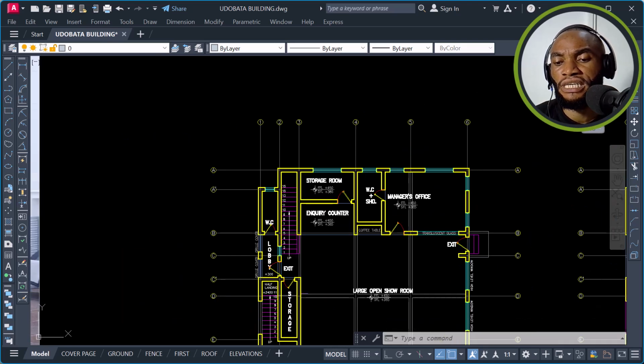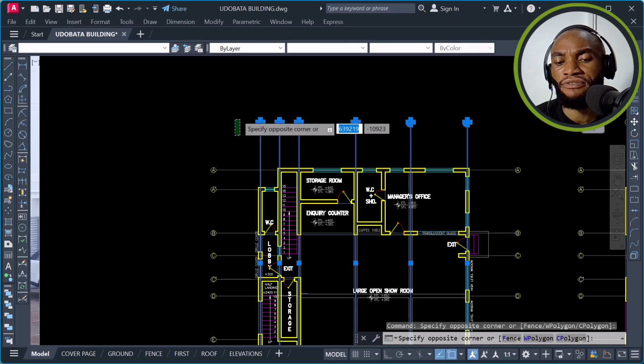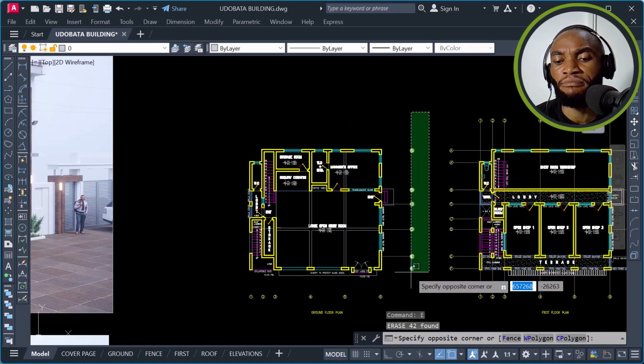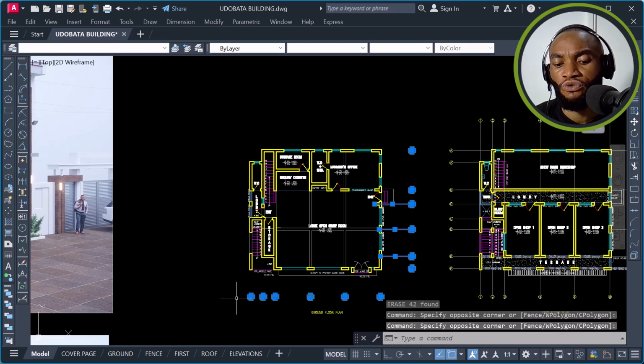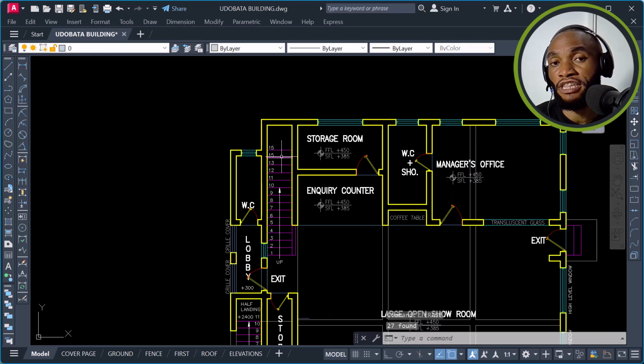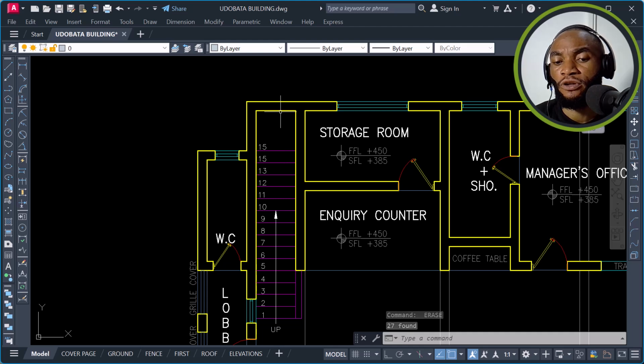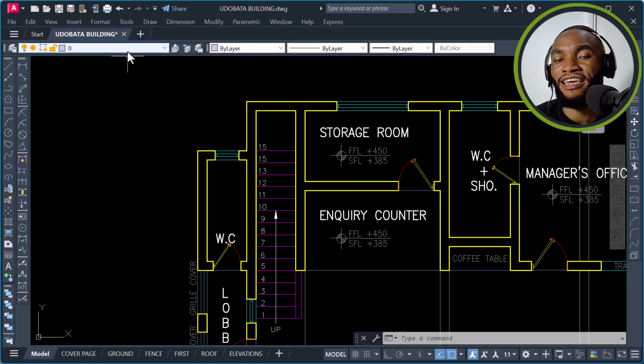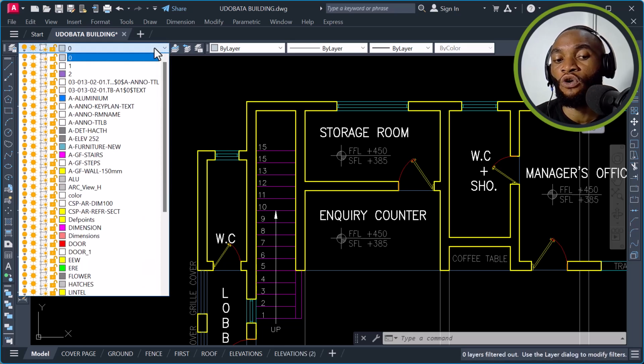Now, let me remove all these grid lines which I have here. If I take this off now, you can see this is how most building plans might appear, just like this, without a grid line. When you have this, the first thing to do is to create your grid lines, which is also called axis. Now, since we're using the software ProtaStructure for our design, we are going to create a layer and call one grid and call the other one column.